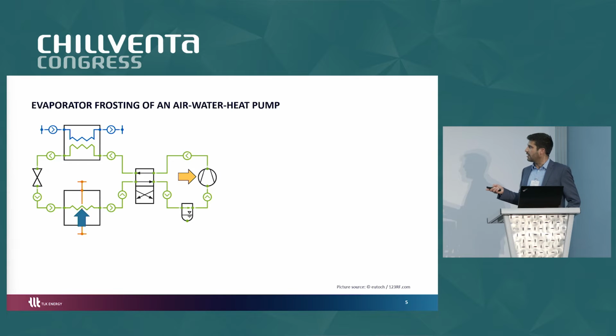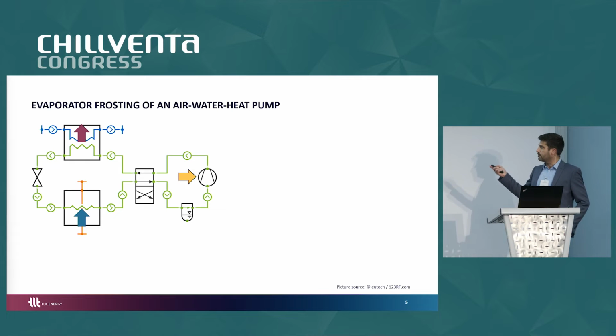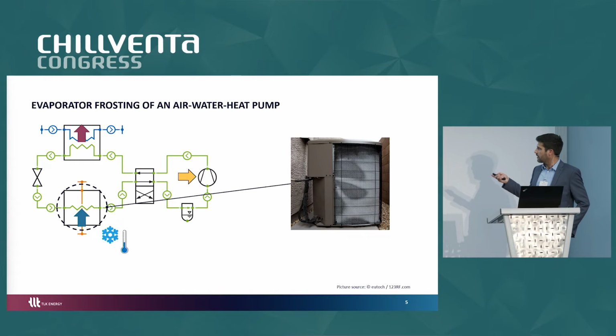And one of the problems for these heat pumps is that in winter, when you have cold and humid ambient, ice can build up on the evaporator, and this, of course, lowers the performance of the system, and then you need to defrost your evaporator.